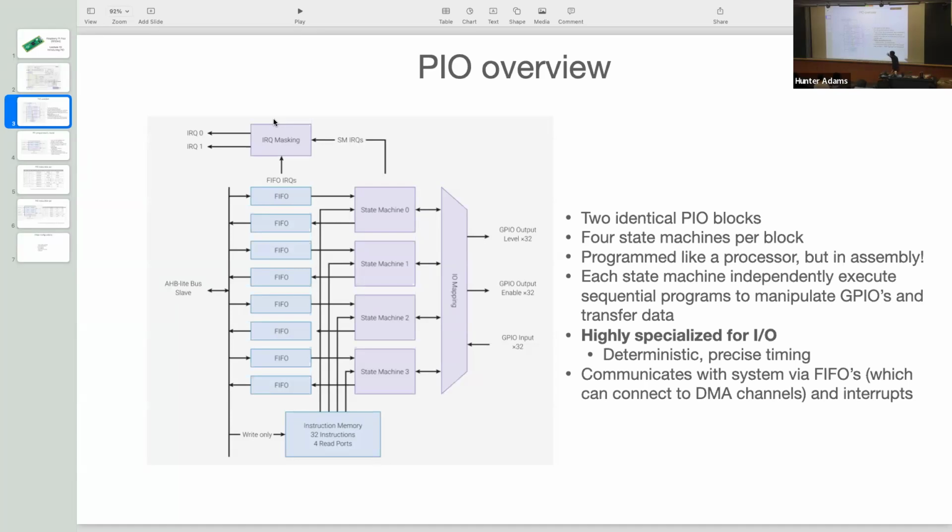I've used a PIO peripheral to build a CAN interface into the RP2040. Controller Area Network, I think is what this stands for. This is the bus that implements data flow in a lot of vehicles, forklifts and cars and airplanes, to my knowledge, and that kind of thing. You're unlikely to find a microcontroller with a CAN peripheral built into it, but with the PIO, you can build your own custom peripheral into these things. So that's part of what makes them so interesting.